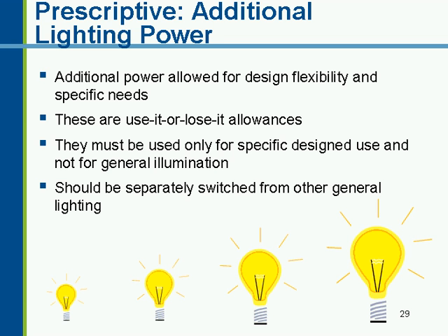This provision for separately switching was reinforced in the 2007 version with some tougher language, noting that it must be automatically controlled separately from the general lighting, and it needs to be turned off during non-business hours. So a little tighter language there.